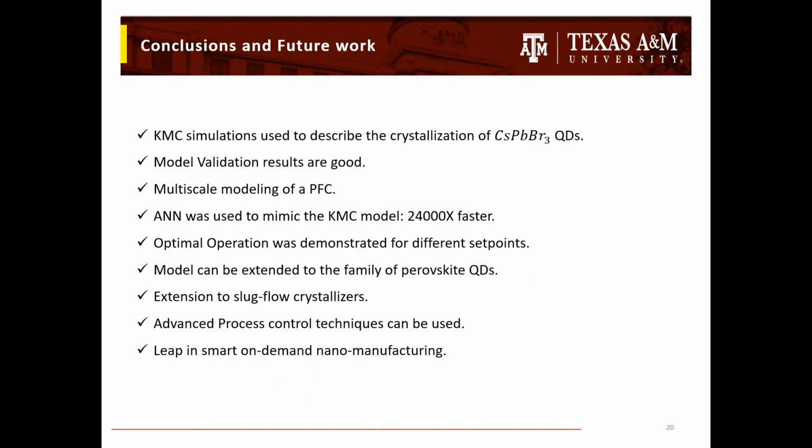In conclusion, we used KMC simulations to describe crystallization of cesium lead bromide quantum dots. We validated the results for a plug flow crystallizer, and it was good. We set up a neural network model to run the optimal operation faster. We showed a case study for a set point case, and showed that set point tracking is actually possible.